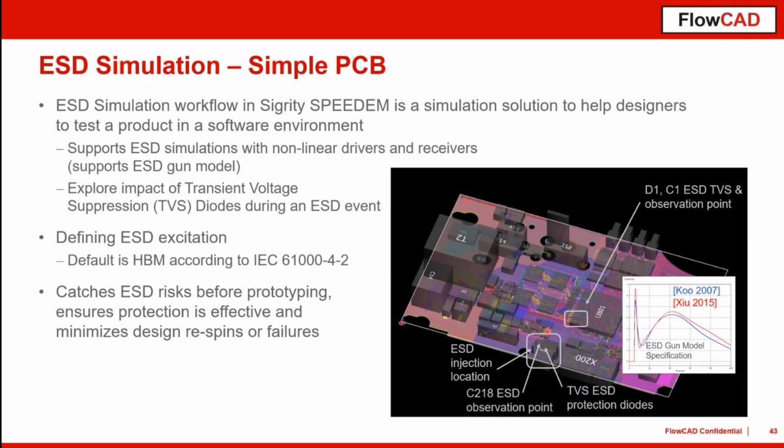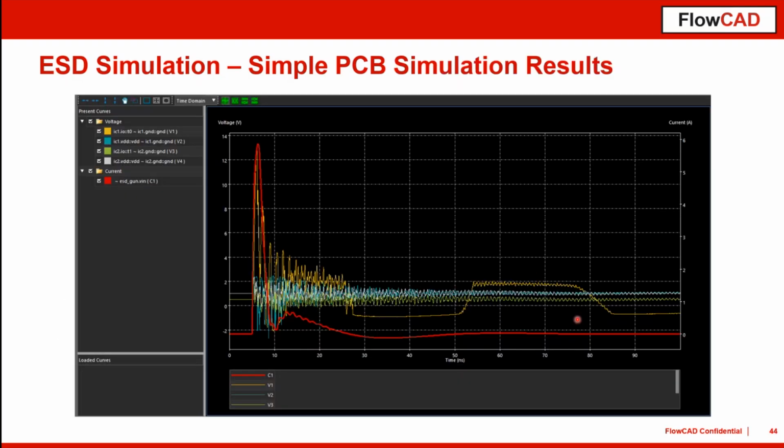If you inject this ESD pulse into the design, you can see how the current and voltage is distributed through your design. That also includes some ESD protection diodes or capacitors, or how this is distributed through your ESD protection schematics. And at the end, you can see if this high current is damped enough. This is an example that comes as a result.